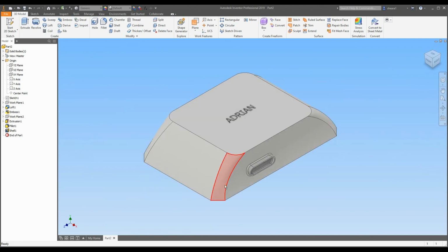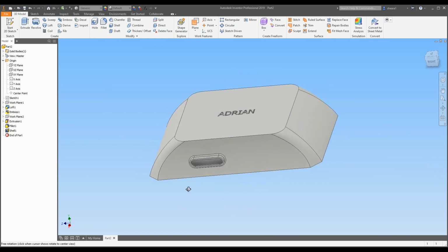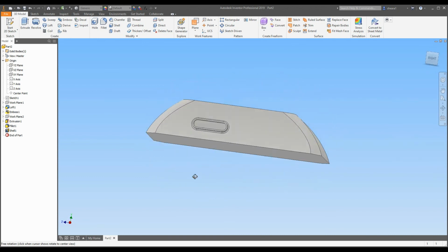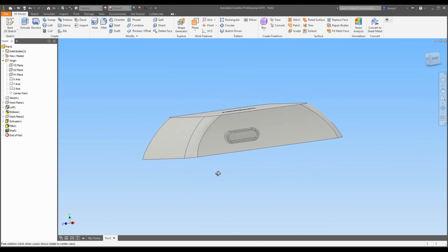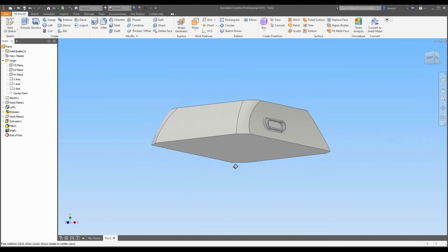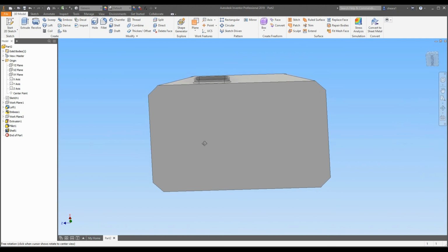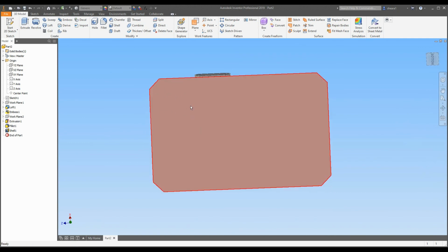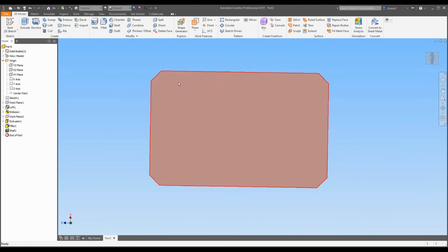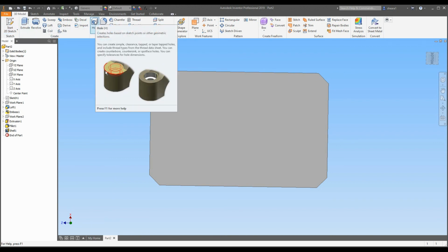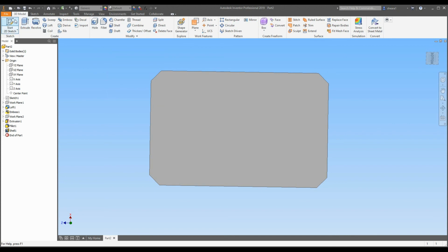Now let's say I wanted this box to be mounted on something. Let's say this is a wiring box, and I want it to have some form of mounting. If I wanted to put screws or maybe nuts through this box in order to attach it onto something, I would have to put holes in the bottom of this box, right? It's very easy. So today I'm going to be using the hole tool, and I'm going to be automatically adding some tapped holes to it.